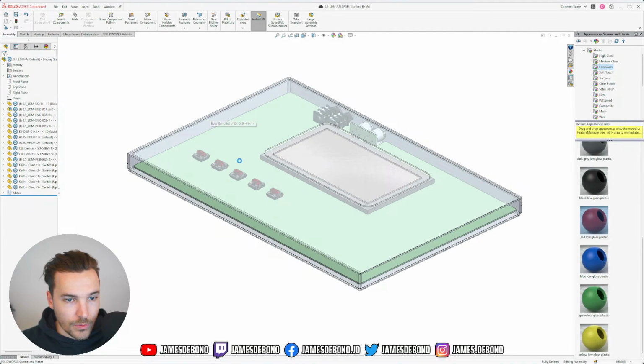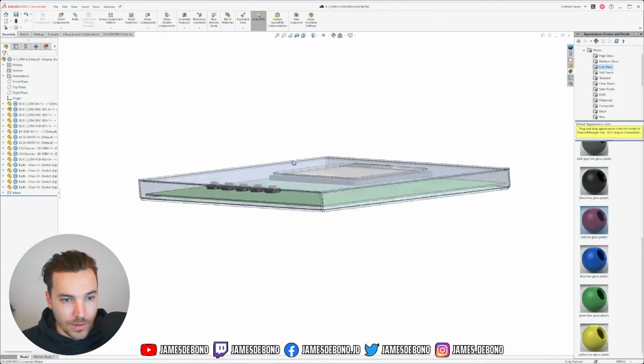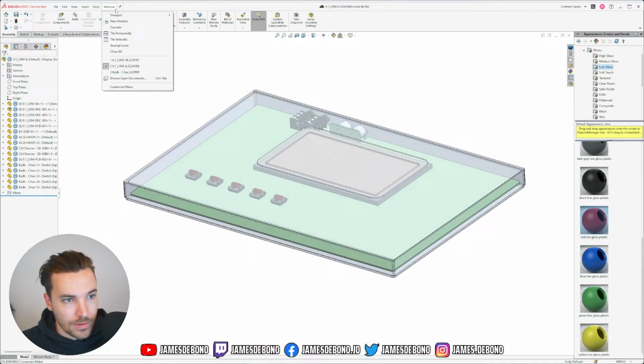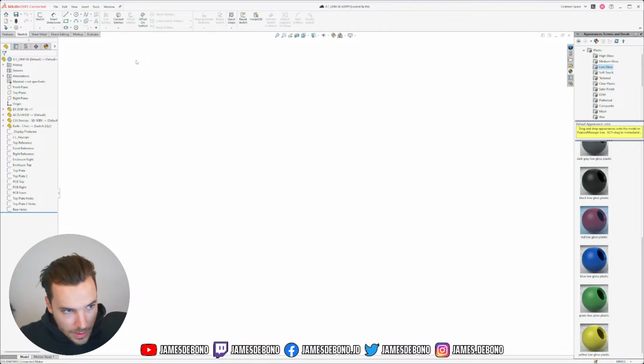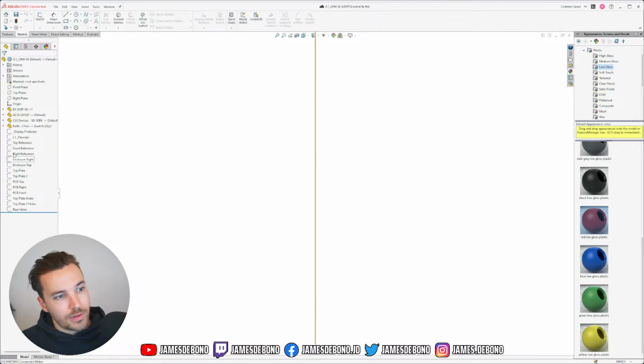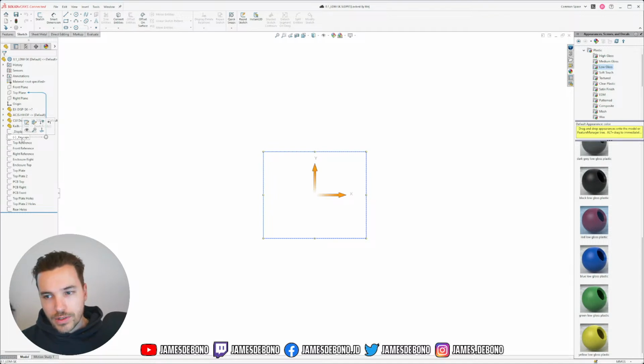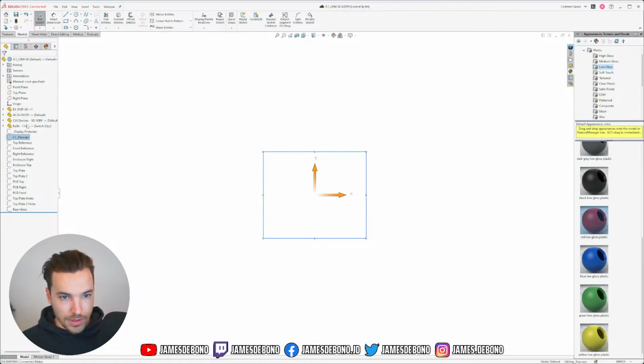It's going to be custom for this device. Sometimes when I make custom components, I'm like, should I make this in my component library so I can use it on other products? But no, the height of the keys on this are going to need to be very specific to the height of the PCB, where the PCB is positioned.